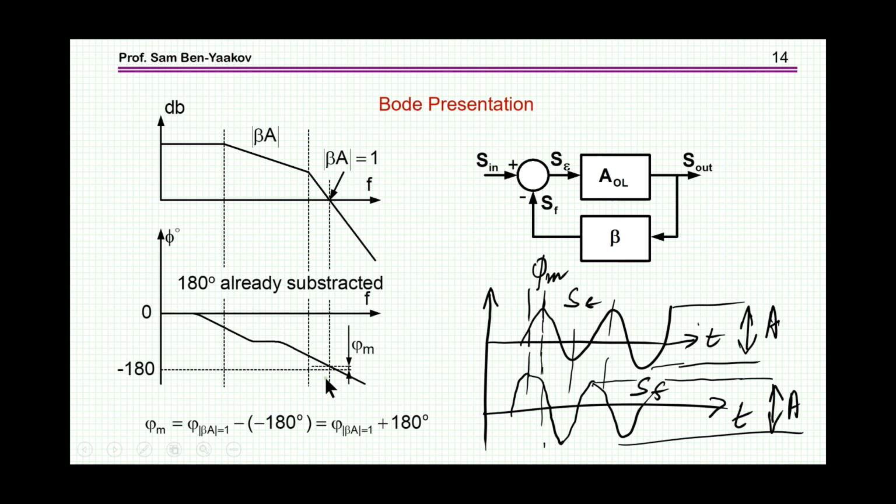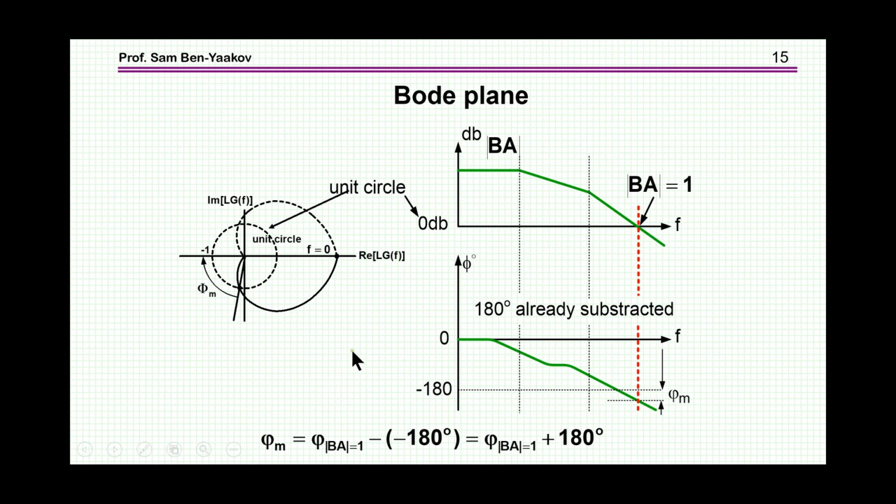But as it turns out, we can look at the phase margin, that is how close we are to this point, and tell some things which are important in the behavior of the system in closed loop. So let's go back again. We look at the loop gain when it is 0 dB, and then we look at the phase margin, and here this system is unstable because we call this a negative phase margin, because we are beyond the 180 degrees.